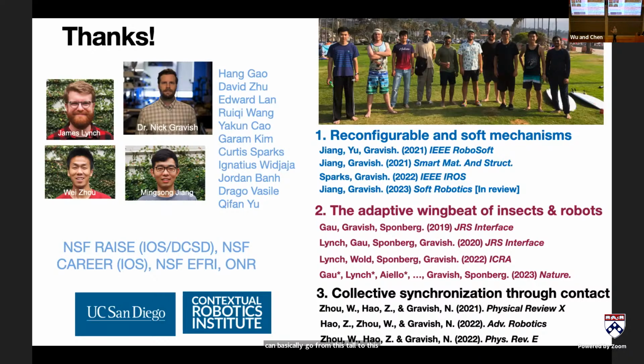And the key to that, which I didn't talk about specifically: if you take a tape spring and you push on it, it'll buckle extremely easily because it's got a weak side that it wants to buckle on. If you take two tape springs and you laminate them together, you've now made a tape spring that has a high tensile load ability. And so we're not using any of the bistability aspects of the tape spring itself. We preform the buckle, and the buckle is just there. The buckle meaning that's our joint.